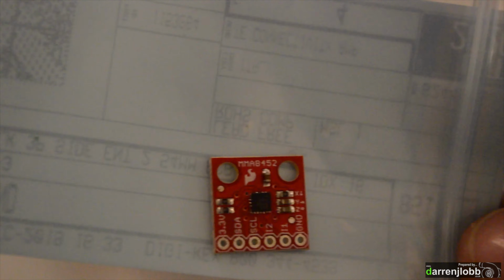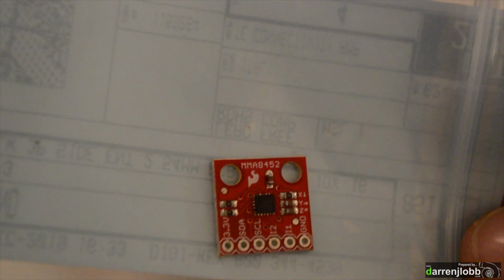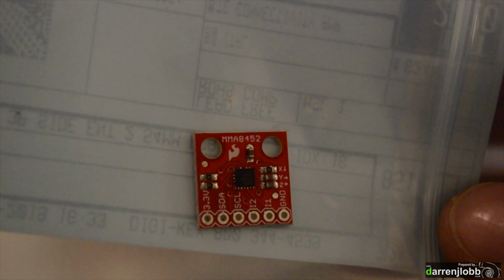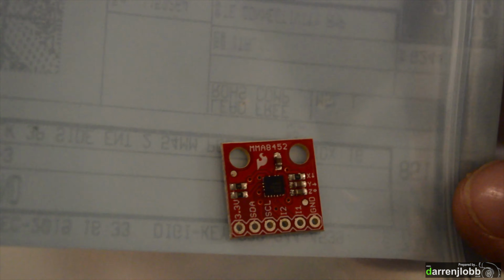If you're going to mount the board on its side, you'll need to use a 90-degree one, so that the board is the opposite way to the PCB, so that this unit is level with the axis of the tractor. Which way you rotate it doesn't matter. You'll just need to select whether you're using X or Y in the Arduino code. There's a little section in the setup that you can see to just flip it between one or the other. So it's fairly straightforward. In my case, I'm going to be mounting it level, so we're going to be using the straight connections.